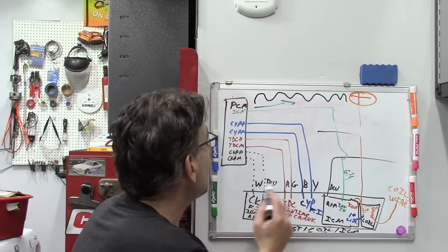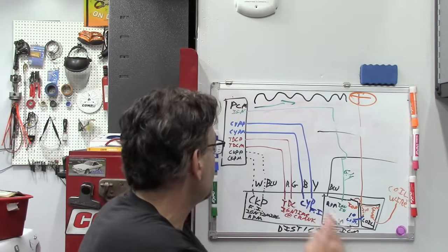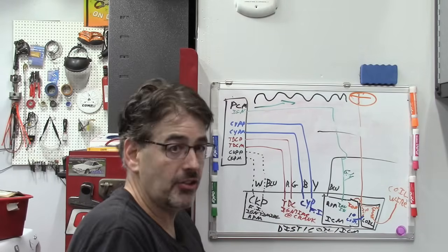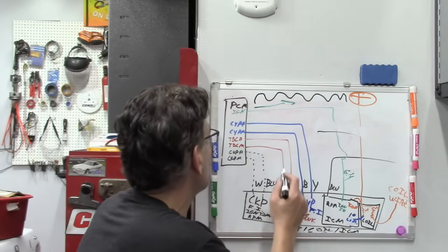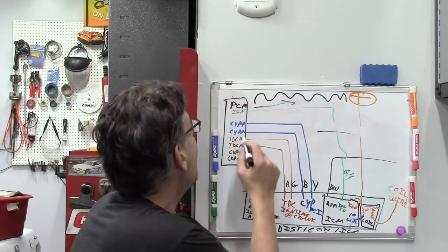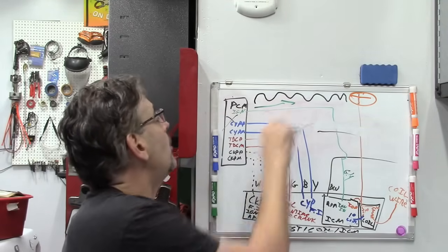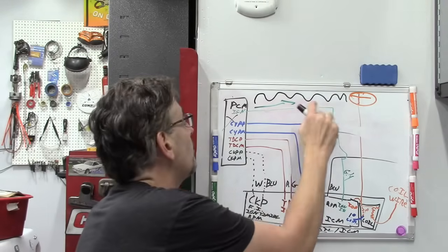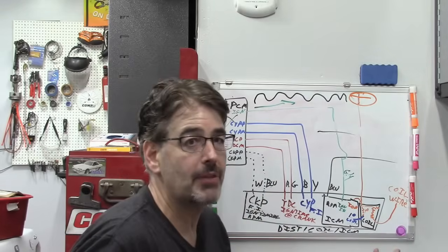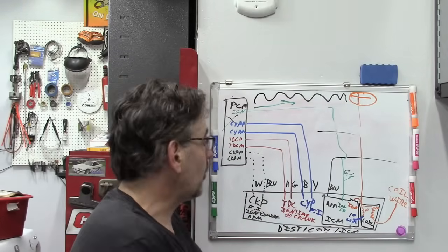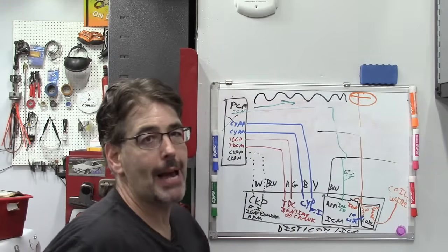Well, one of them would be any sensors here that are responsible for that square wave production are failed, and of course replacing the distributor would ultimately fix those. Or we could have it where the signals are functioning and they're reaching the PCM, but the PCM is bad and not putting out an ignition signal. It's also possible we just very simply have an open wire or a short to ground or something in the ignition wire. So replacing the distributor is not going to fix that. It wouldn't fix a bad PCM.